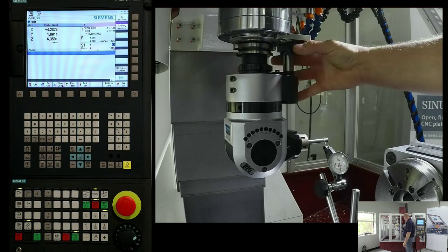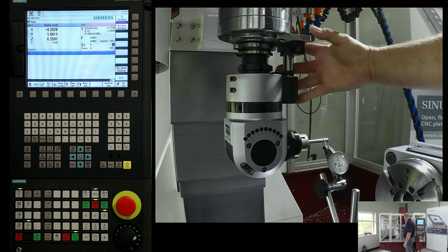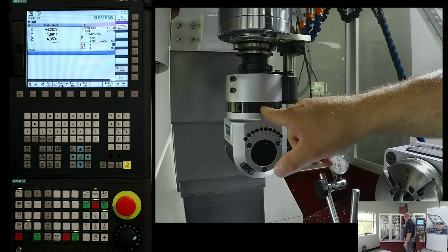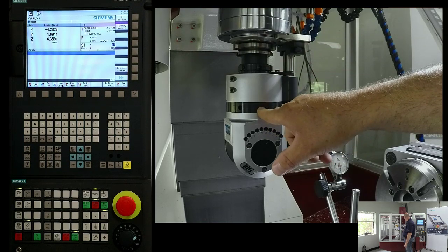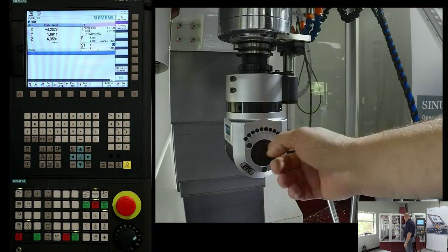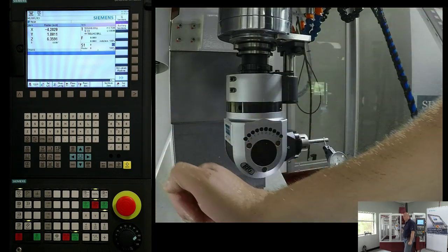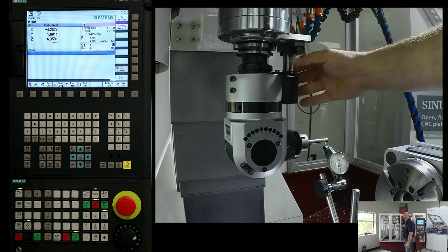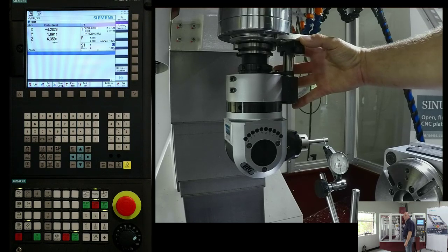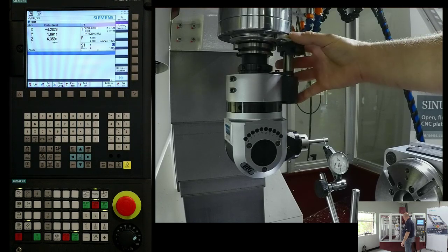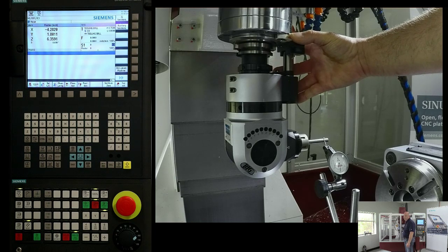So what I did was I made sure when I machined this block and I set it up that when I had this scale set to 0, my spindle itself was straight or aligned with the x-axis. So I would have indicated it straight, and I made myself a little bit of adjustment here so I can basically tram in the head. So that was setting my base 0 location.